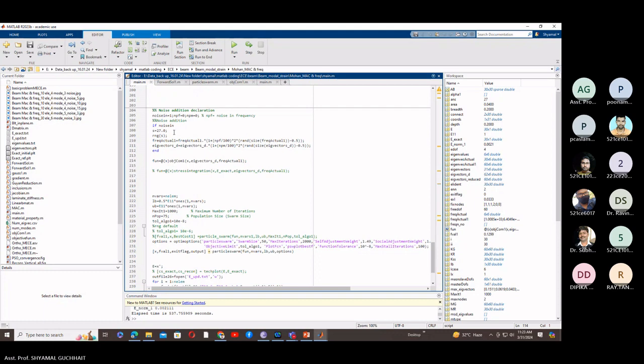During the PPT presentations, I told you that if we do damage detection by numerical coding, first we can do the FEM analysis to get the measured data. Here, for free vibration analysis, our measurement data are the natural frequencies and mode shapes. In the real field, the measured natural frequencies and mode shapes will have noise. To simulate that exact behavior, we can add some noise in the natural frequencies and mode shapes.